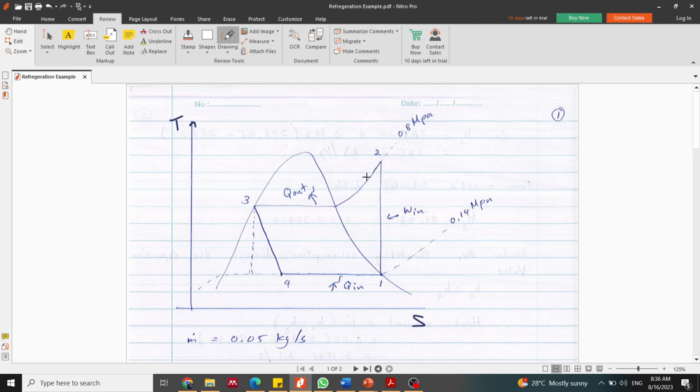Then we have the heat rejection process to the environment, which happens in the condenser. What the condenser does is remove heat to the environment so that the refrigerant cools from superheated all the way to 100% saturated gas, then 100% saturated liquid. Then we have the throttling process in the expansion valve. Normally, when we are throttling in a valve, entropy increases.